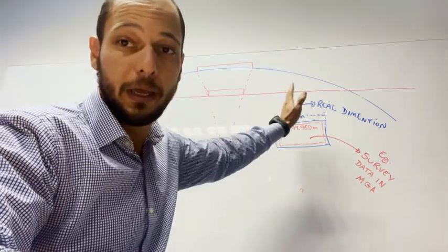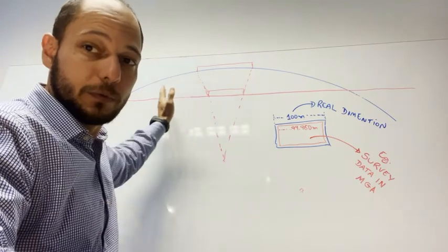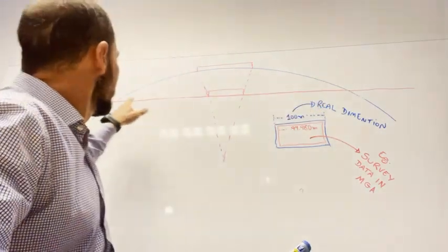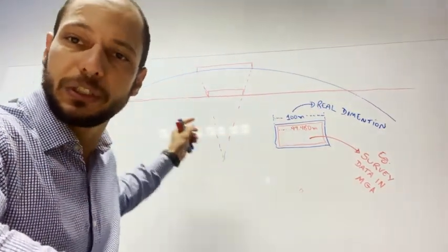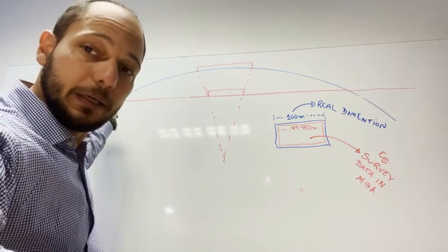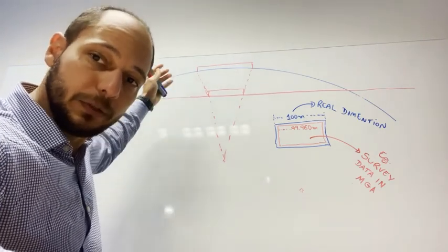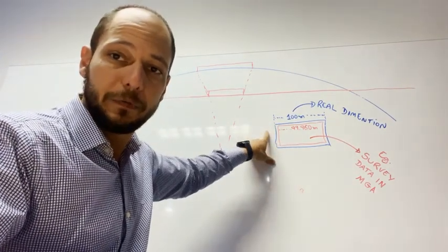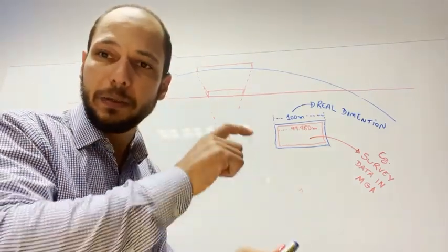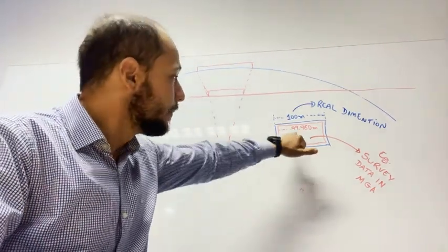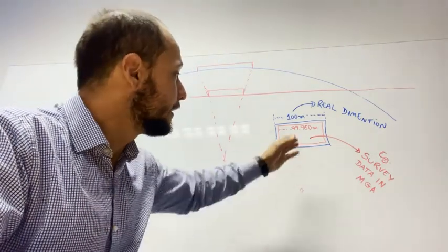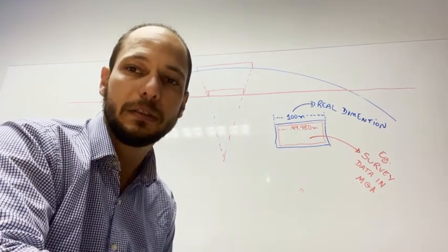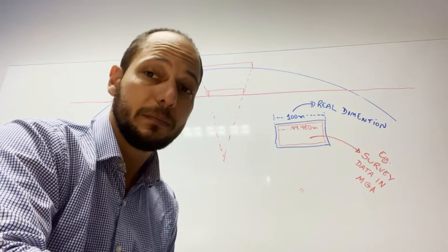And it can vary as it goes to the sides of the zone, or even past the zones of intersection, where the dimension you get on the plans can be bigger compared to the real dimension. So for example, a building that's 100 meters out in the field, if you get the plans and measure the points in CAD, you might find out that it could be, for example, 99.960.